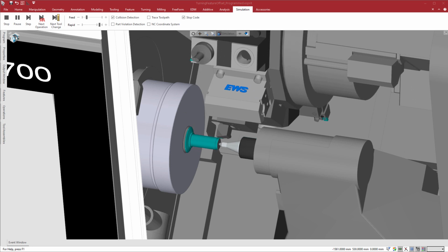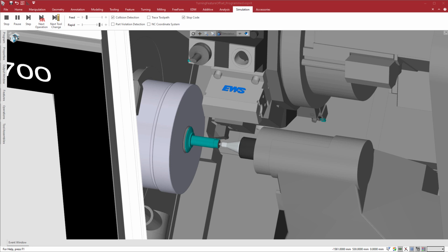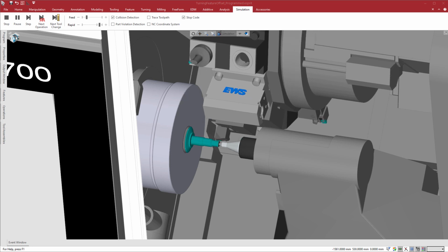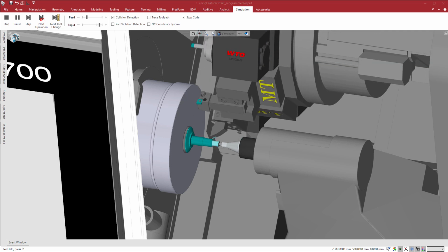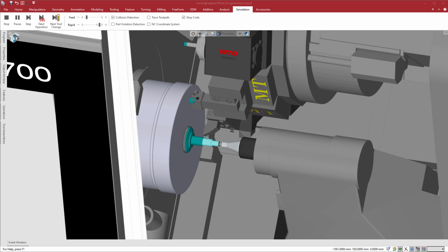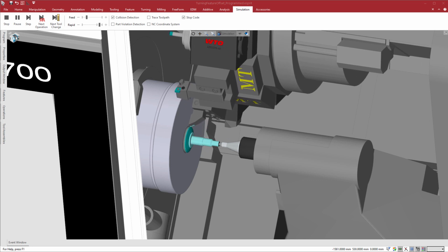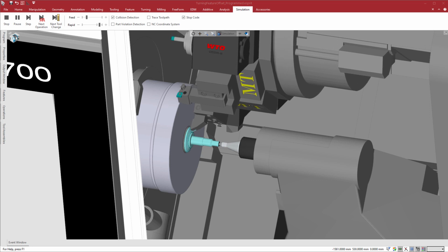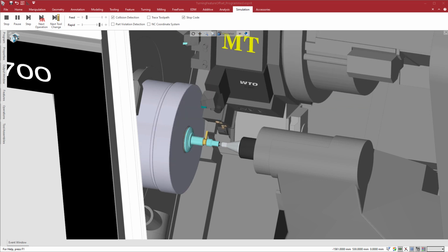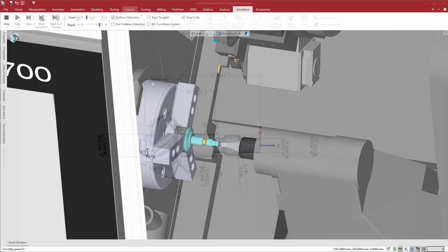Use this selective offset to program center tolerance in cases of unilateral tolerance, or to apply standard ISO code tolerances. You can also use turning feature offsets to leave material for subsequent processes without having to modify the geometry. Selective offset gives you great flexibility to program faster and more precisely.